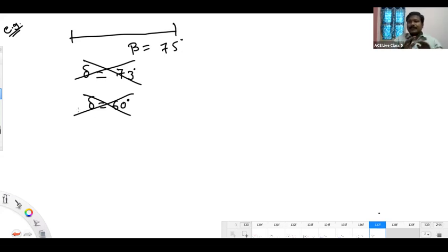For any type of disturbance, the system should not lose synchronism, so we have to set the value of delta. In that view, generally we prefer to take delta in the range of 30 degrees to 45 degrees. These are generally called the preferable operating angles of the system.